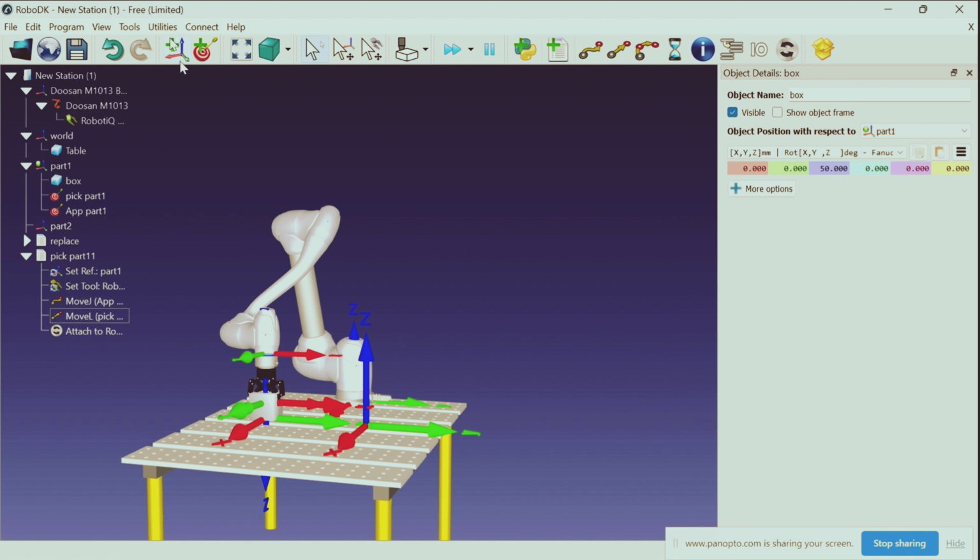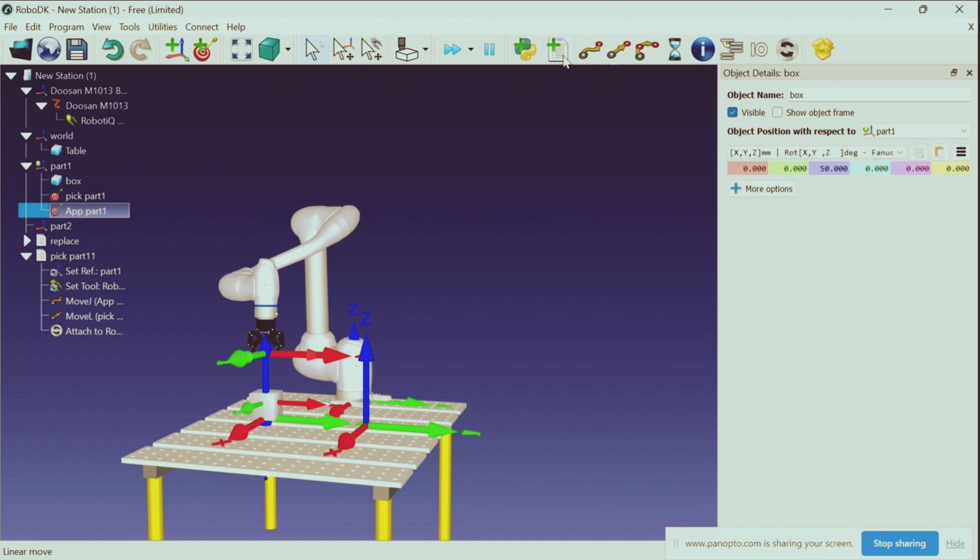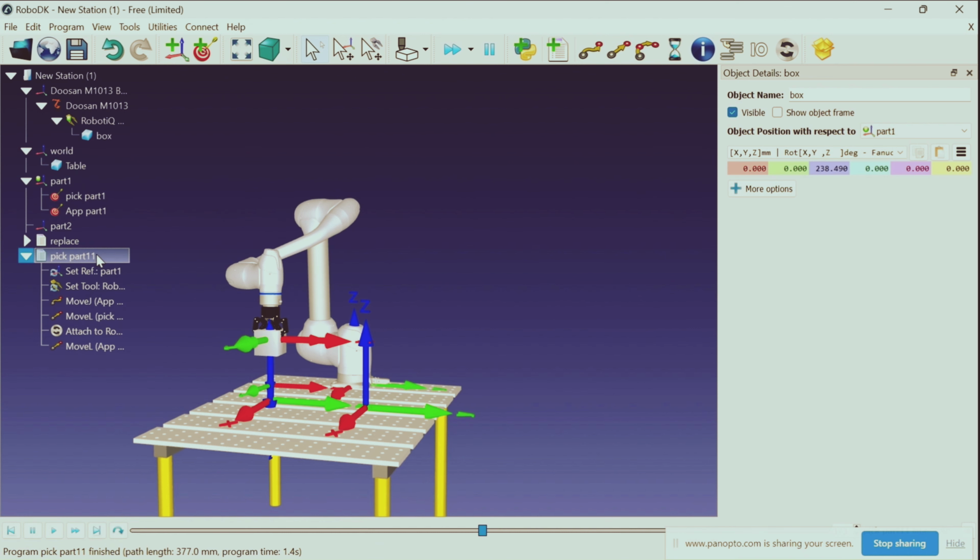Then move to, again it should pick and move up, no? So then you need to take this position, right? Then you again give the move L command. Okay. See, now you run this program, it is picking up. Now, okay, it is picking up. So operation is success.